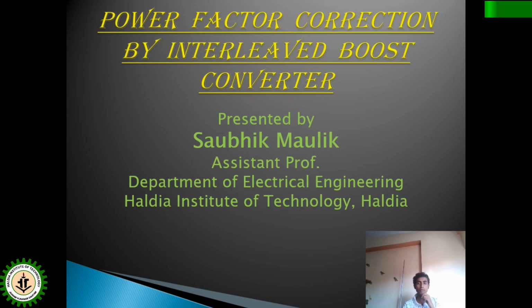So we are discussing the topic of power factor correction by interleaved boost converter. Already it is discussed why power factor correction is required for AC to DC converter fed loads. Because in case of rectifiers, the output voltage that we get is in the form of pulsating DC.